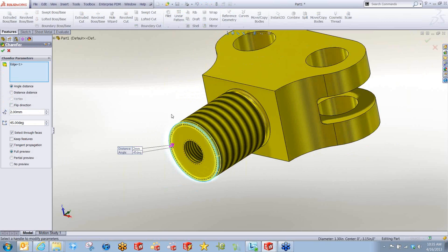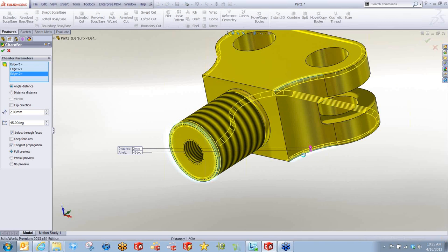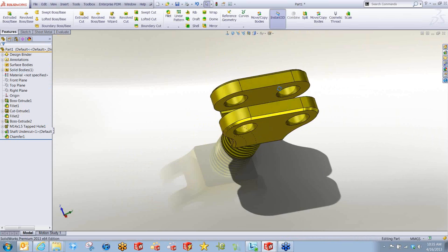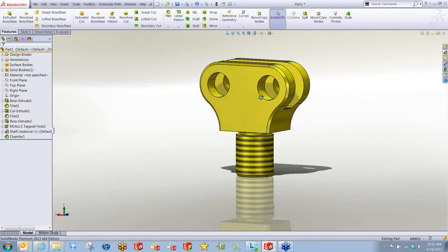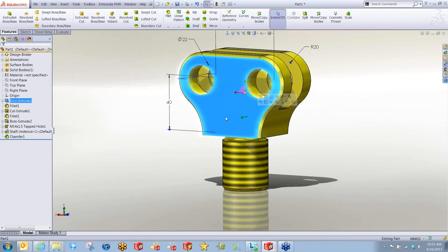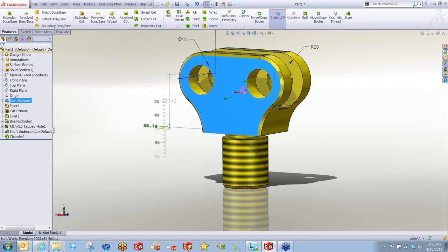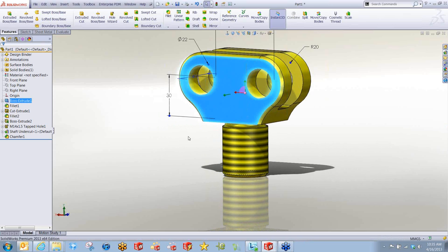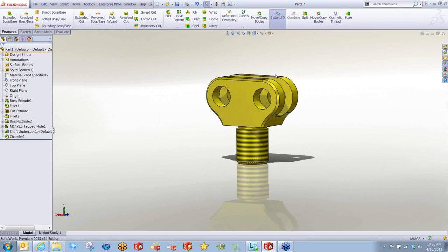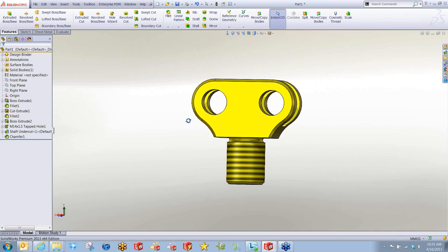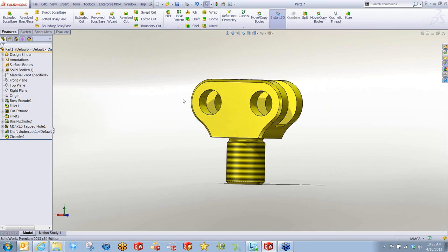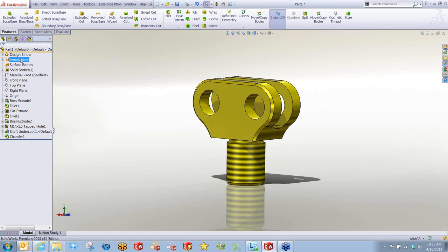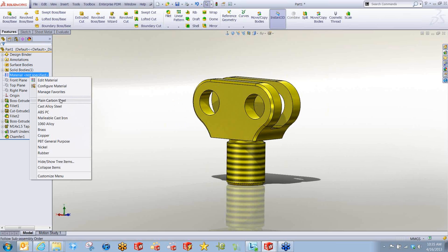Okay, and now I'm going to go ahead and chamfer some of those hard edges we need to get rid of. We'll throw a chamfer here and then over here as well. Okay, now I've got the geometry I like. But now that I've got this modeled up, I'm realizing it's a little long. Well, I can edit dimensions as if I was creating them for the first time. Okay, even after the fact, I can go back in time and make those changes, and you see everything updates appropriately.